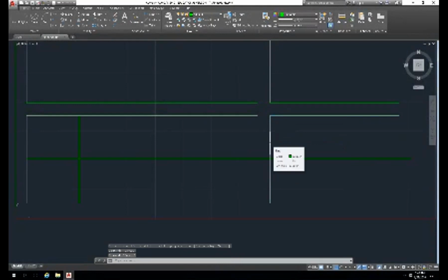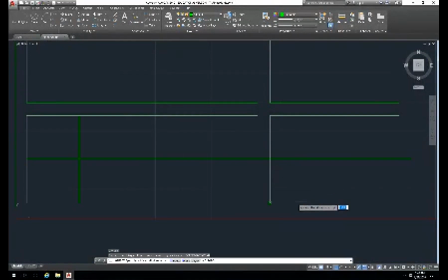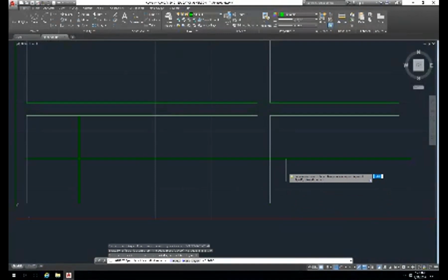Okay, but I do need this chamfer. Well, actually not necessarily. I have 1.50 minus 0.44. So do the offset, and we say 1.5 minus 0.44. Just recently I learned that you can enter dimensions or commands that way. It requires numeric distance, 2 points, or option keyboard. Specify offset distance. Well, the other rule is keep a calculator next to you.